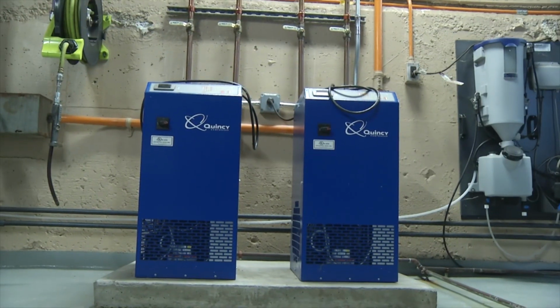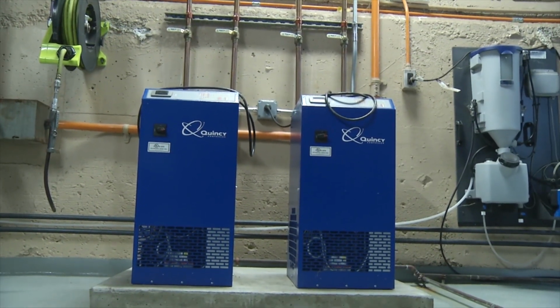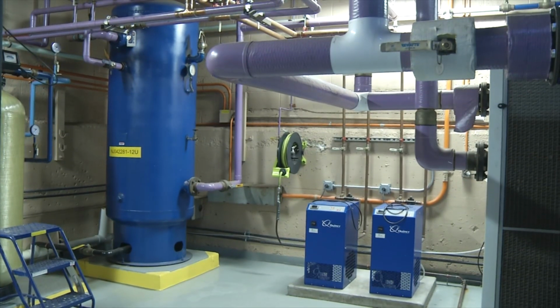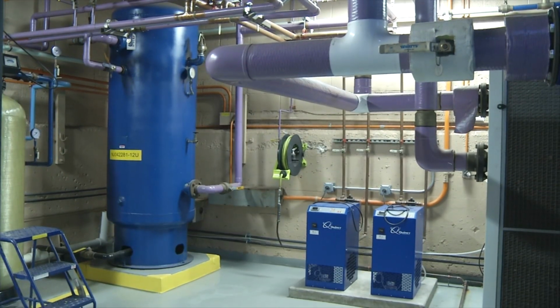For example, they won't be attached to a cooling tower, and they'll simply be air cooled. You can improve the performance of these by lowering the condenser temperature using a cooling tower the way you would with any kind of chiller system. This is something you can think about if there's a lot of energy being spent on drying, but I'd like to point out that we only need to cool the volume of compressed air being used. The CFM is normally not very large.